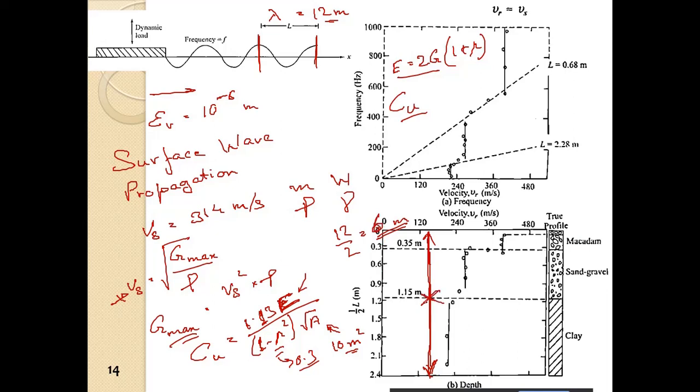Now what is the stress at this point? That is at this 3 meter, so we can take that as the mean stress, sigma v. So the mean stress here, we will take sigma z is equal to 1.8 into 3. That is the mean stress here.